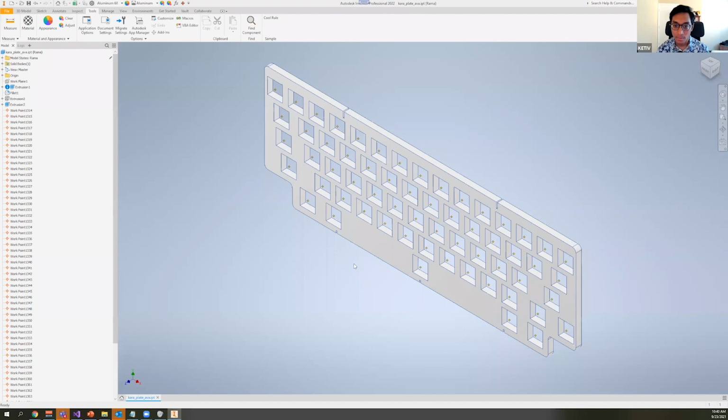Jared Angulo: on the topic of grounding versus constraining, is grounding preferred in this case because the positional logic is contained within the code itself rather than relying on Inventor to set up? I would argue, yeah, exactly. Because with constraints, a lot of tools in Inventor require a series of inputs and outputs, and not necessarily inputs and outputs that we're interested in as designers per se. It is stuff like, we need a point and a direction for this thing to point so that we could orient it properly on a UCS or something, right? And so by taking that step out and just having the position be the important driving factor, we end up not having to worry about the additional requirements that these Inventor functions require us to have.